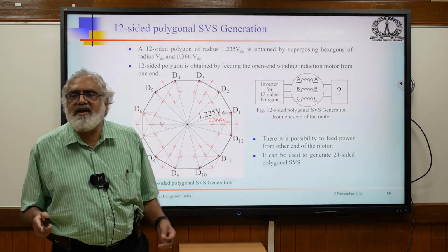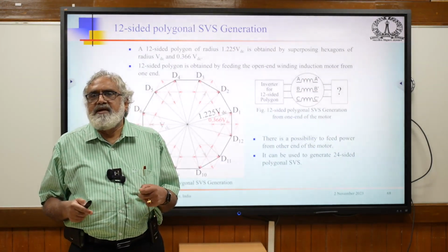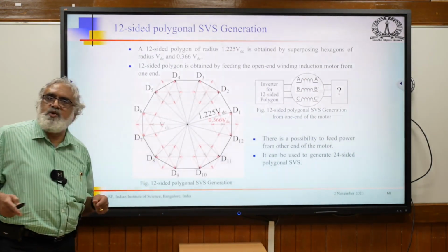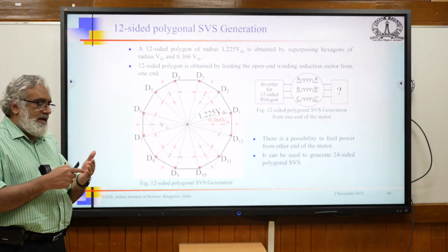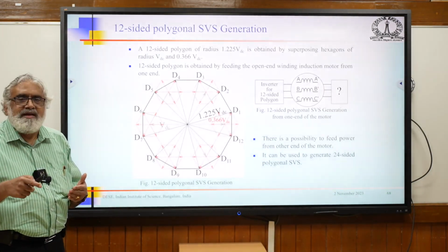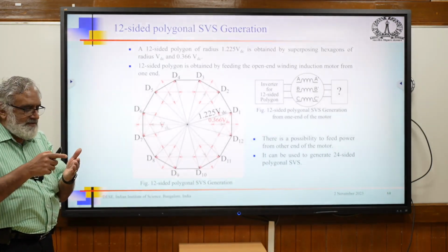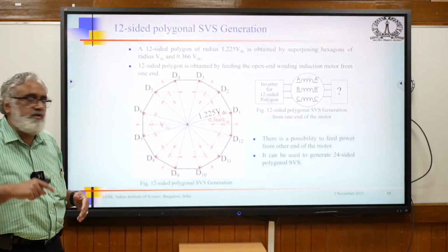So instead of switched average, can we get a stepped waveform throughout the modulation range? So we thought about, can we get a 24-stepped waveform throughout the modulation range? If the space vector structure has many concentric 24-sided polygons, then we don't require PWM. As the speed varies, move from one concentric hexagon to another one. And 24-sided throughout you can get it.